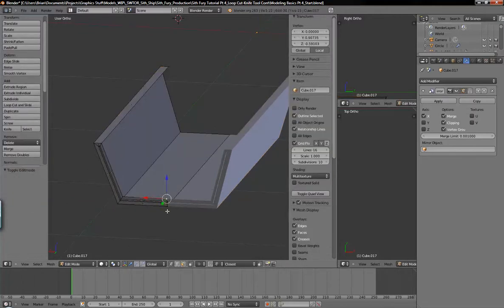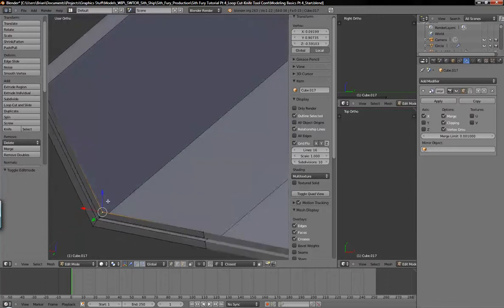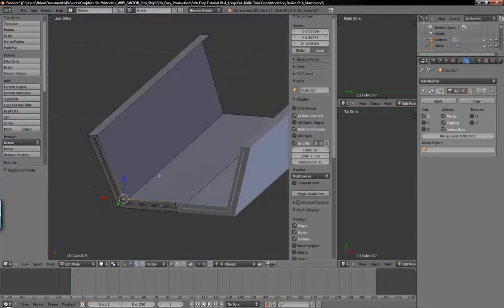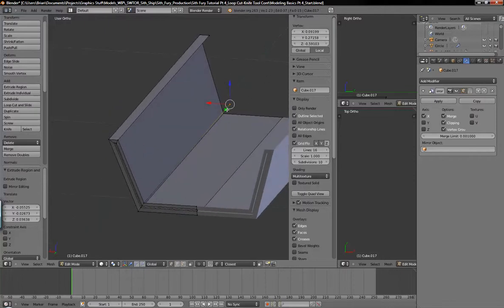First I'm going to go into vertex select. I'm going to extrude this point here back to match this back point. So we're going to select this back point and just make a note of the Y position of the vertex. Select this top corner one here. Now hit E to extrude, and then click in the Y field there, and it's 0.27, oops, 7158, and enter. And now that is in the same position as that bottom piece.